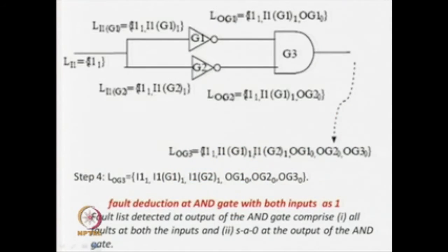So then we started discussing another algorithm, in which case can we do the whole thing in one go? That is, we apply one random pattern, and in one scan of the circuit, can we deduce the results about all the faults that can be detected by this? Then we saw that deductive fault simulation was a very good approach for that. We apply one random pattern, and then at each net of the circuit, we find out the fault list that is detectable by that random pattern, and then in one go you can find out which faults are detectable by that pattern.